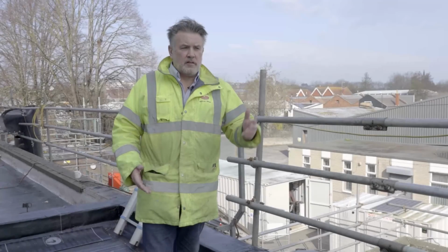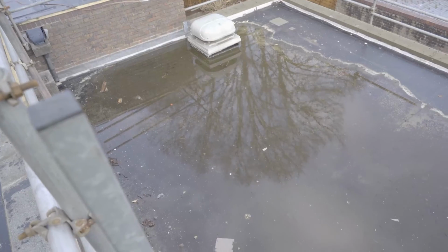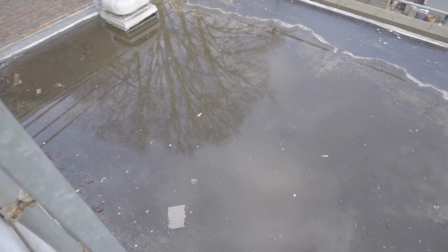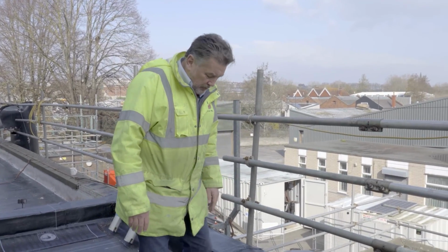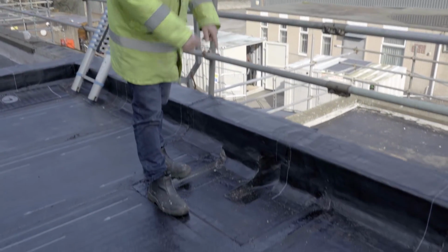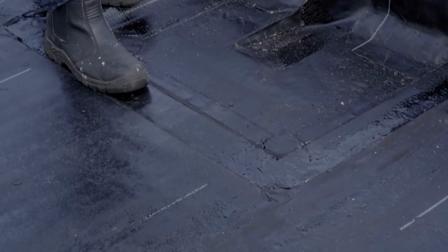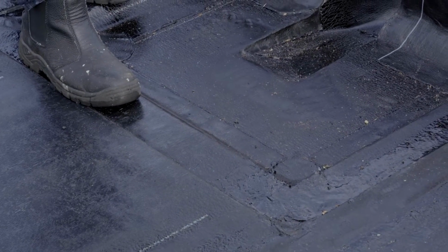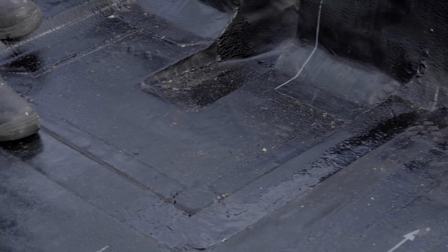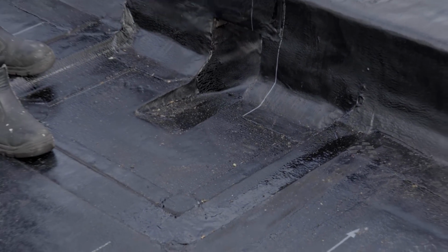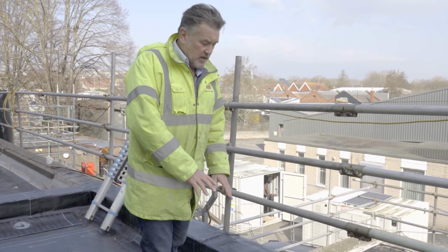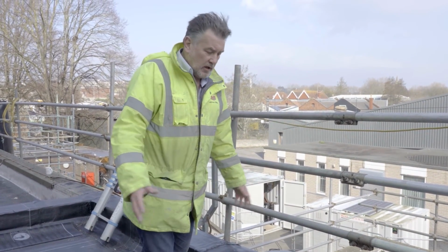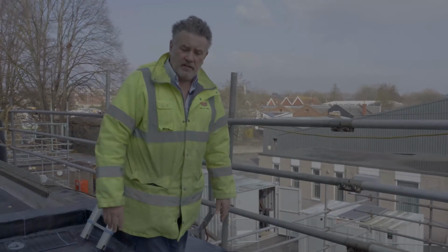So what was evident on these roofs is that there was a lot of ponding water. Main reason being that the roof outlets were too high. So we've insulated this roof, we've put a hard edge of timber around these outlets and we're going to endeavour to sump the outlets. So this is what we've done here. So we're utilising the existing falls, but we're making sure that the lowest point of the roof where their outlet is maintained low, and most of the water can be directed into it.